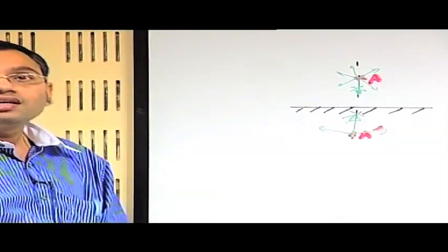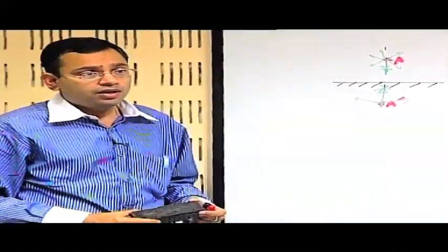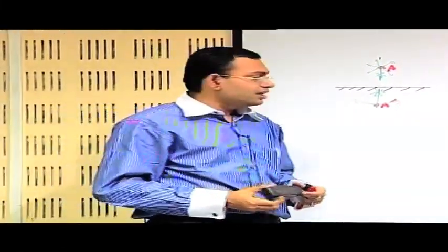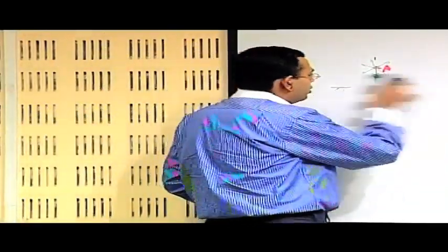Now we have also discussed that not all flows are potential flows. In fact, no flow in reality is a potential flow, but potential flows are important because if it is boundary layer theory that you are applying, then outside the boundary layer you may apply the concept of potential flow, and whatever pressure gradient you calculate out of that is imposed on the fluid within the boundary layer. But because of the existence of the boundary layer, the viscous effects are also important, and that dictates what the drag force on a body should be.